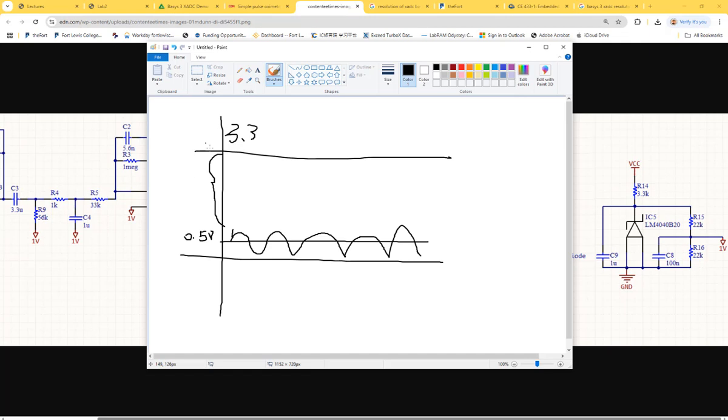We don't have to change anything. I think it doesn't matter. It just looks a little bit odd. But the thing is, using 3.3 volts as a universal power supply is beneficial because it's the same power supply for the IPGA board as well. So instead of using 1 volt, we probably have to change it to 0.5 volts for the DC offset for the amplifier.